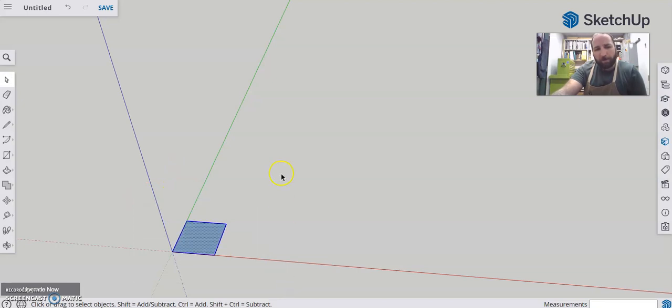And I'm going to select it. Now there's multiple ways of selecting things. I'm just going to drag an arrow around it. And what I'm going to do is make 4 of them. If I hit Control, so I hit M, sorry, let's go back. I hit M for move, and you'll notice that I've got this four-way arrow tool up.